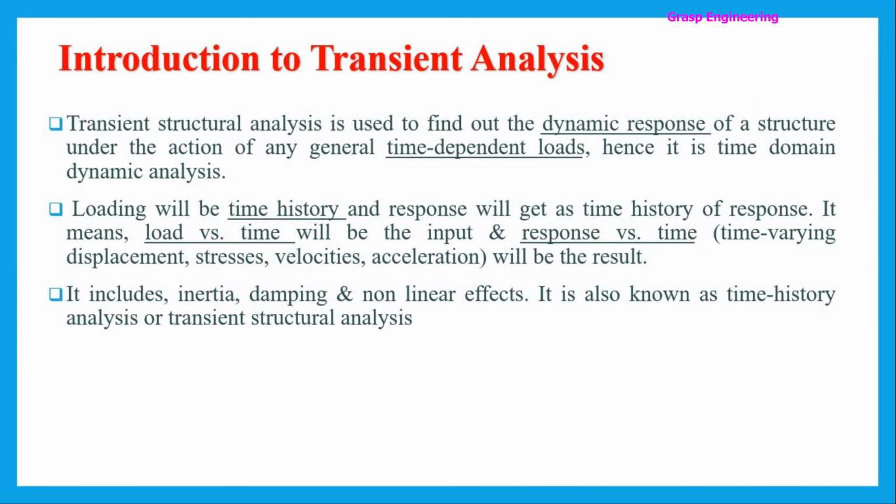This is not the case with other dynamic simulations such as modal as well as response spectrum simulation. In that case, you are not able to capture the nonlinear effect. So this is the advantage of transient structural simulation. That's why most of the time, when you have a time domain response as well as time loading, basically load versus time as we discussed, and also if you have some geometric non-linearity or frictional contact, it is recommended to use transient structural simulation instead of other dynamic simulation.